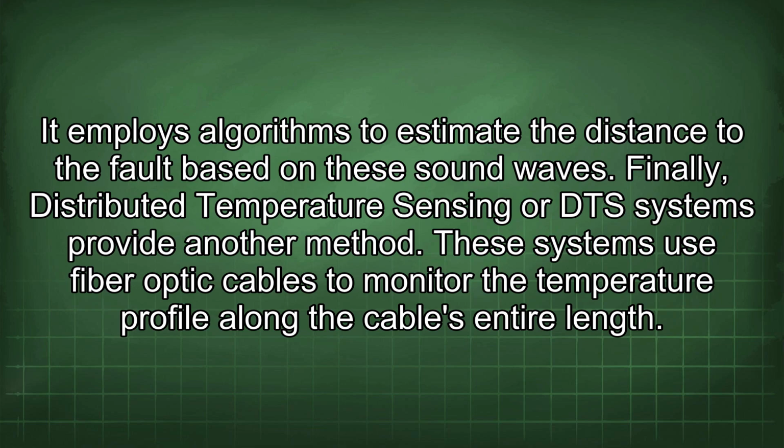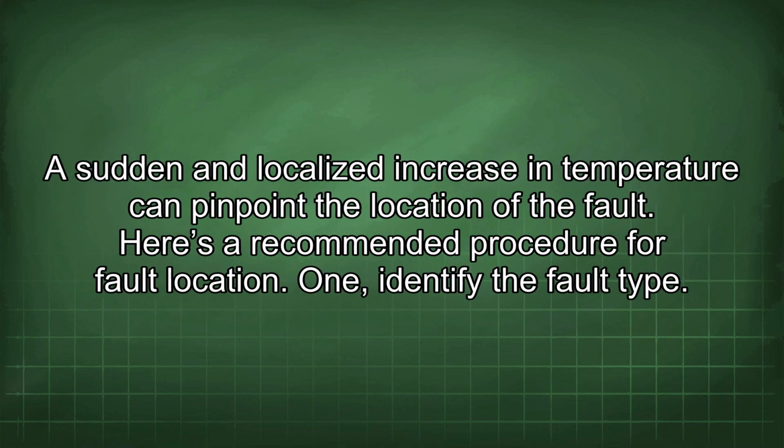Finally, distributed temperature sensing, or DTS systems, provide another method. These systems use fiber optic cables to monitor the temperature profile along the cable's entire length. A sudden and localized increase in temperature can pinpoint the location of the fault.